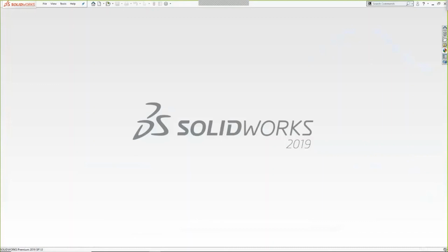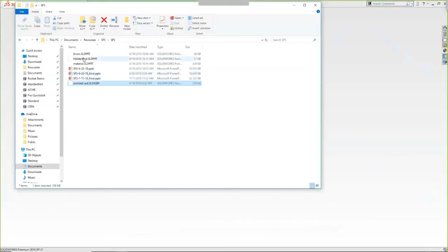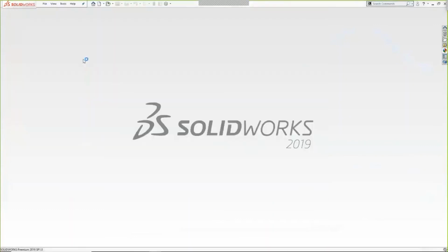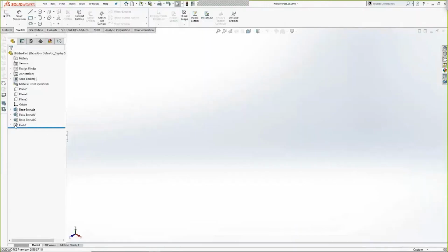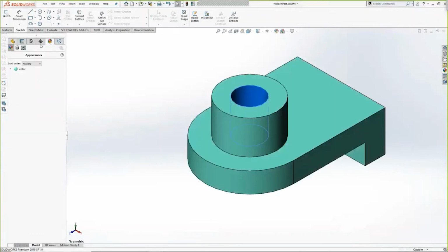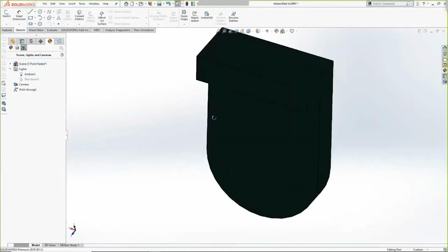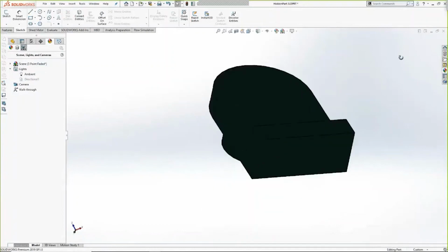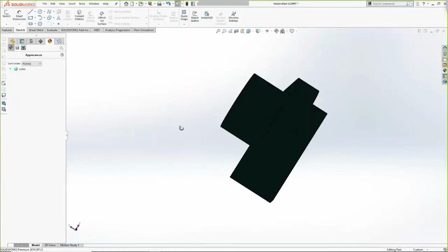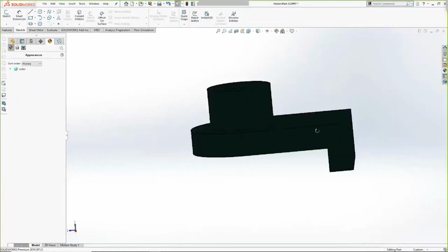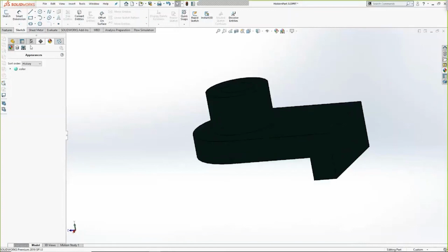One bonus thing I want to show you guys, so let's open up my hidden part again. This isn't actually a part that's not able to be seen, but sometimes what I've seen happen is you're looking at your part and it's completely occluded, it's completely black, you've added a material onto here and it's still not appearing correctly. So what's going on here is there's no light shining on your part.